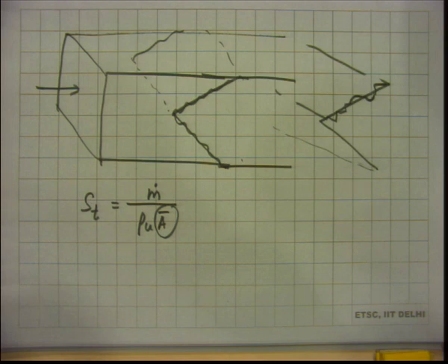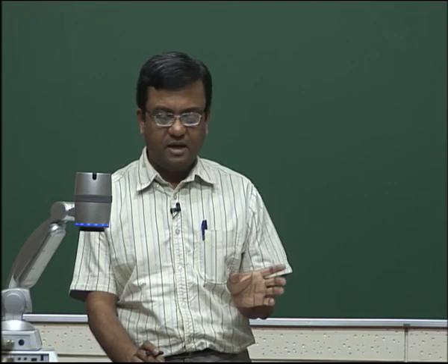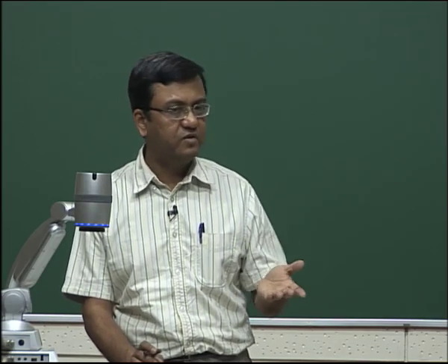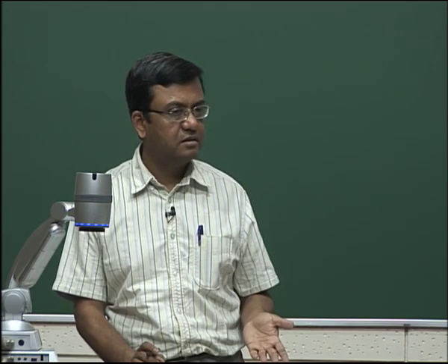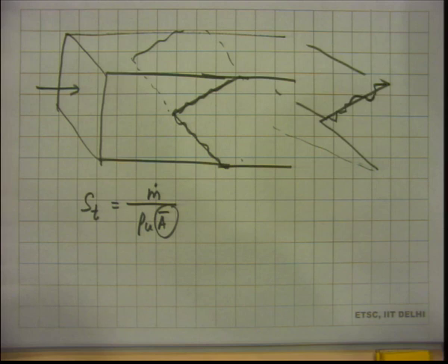Okay. If we wanted to use the entire flamelet area, then we can use A flamelets multiplied by rho u and multiply that by which burning velocity? I think I briefly mentioned that in response to your question yesterday, when we were discussing the Damköhler model. So, if we use A flamelets, then we can use SL, right, we can use SL. So, SL is associated with A flamelets and ST is associated with A bar, which is the averaged flame area. Now, which area is larger? A flamelets. So, which velocity is larger?